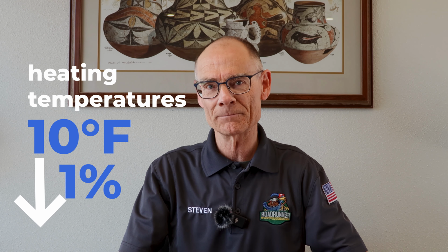It is based on 30 years of climate data, 24 hours a day times 365 days in a year. Every one of those hours has a temperature assigned to it. So the 10 degrees number is the 1st percentile number of the heating temperatures in Santa Fe, saying that fewer than 1% of temperature hours are typically lower than 10 degrees. And then on the upper end, 90 degrees, fewer than 1% of the temperature hours are hotter than 90 degrees. So we have captured 98% of the temperature hours that this home will face, and that's where these load calcs are based on.